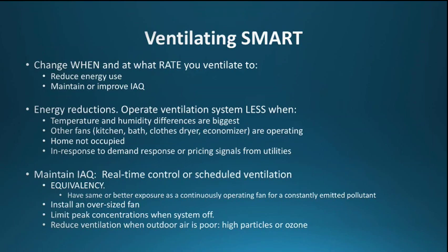In order to do that, you have to install a fan or a ventilation system that's oversized compared to the steady state, because sometimes you're going to have to ventilate more if you wish to ventilate less at other times. And you do have to worry about peak concentrations that might happen by not ventilating for a long time and then over-ventilating for a long time.